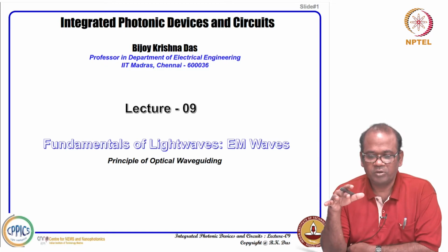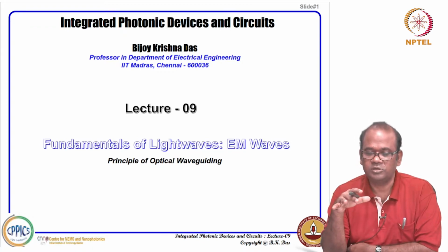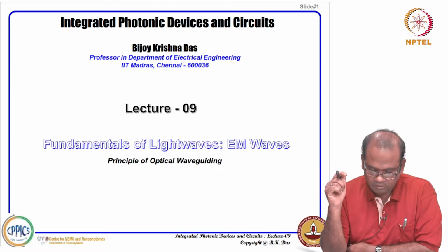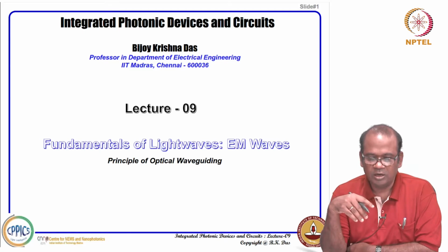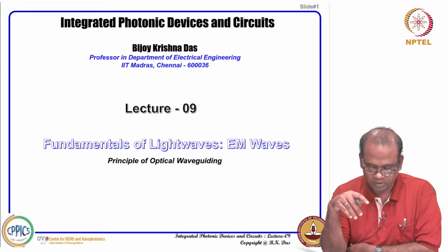To understand the optical waveguide, we have discussed a bit about electromagnetic theory, Maxwell's equations, plane wave propagation, etc. And today we will be discussing optical waveguiding. If an electromagnetic wave is operating at optical frequencies, how do we design an optical waveguide?